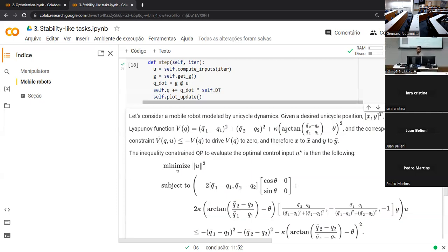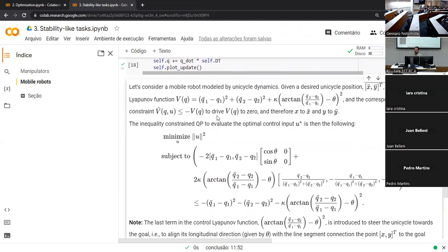That comes from the fact that these robots have so-called non-holonomic states. So the unicycle is not able to slide sideways. Otherwise, it would be trivial to move a point right on the plane. In this case, you need to steer and then go. Right? And this is just done by defining this function, like two quadratics summed to each other. So extremely easy.